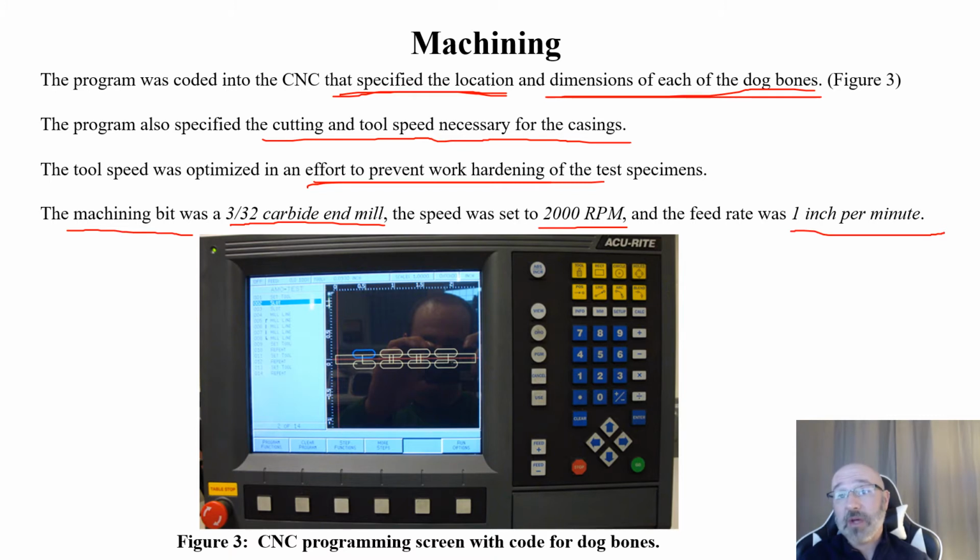They might already know, okay, this is a brass material, we don't want work hardening, so I have a rough idea of what speeds, feed rates, dimensions, cooling, and lubricant I should be using. Or do you want to do that research on your own, calculate it, and tell the machinist what to do? Or, best case scenario, you do your research, figure out what you think is best, and then work with the machinist who has that experience and collaborate together, if that is an option for you.